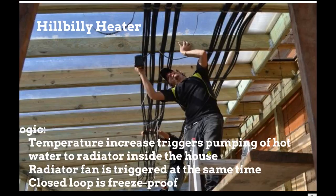So let's talk next about the heating system. The Hillbilly heater is just a passive solar thermal heater, a closed loop system that we're running into the house with a fan radiator. And the logic there is, once it's daytime, it's hot, this is winter, let's say, and a certain temperature is reached, you start pumping the fluid into the heat exchanger inside the house, and you turn on the fan to spread the heat in the house. So you're transferring heat from the greenhouse into the house, which is a simple thermostat controller that works with a radiator that does forced air as well as pumping of the fluid inside this Hillbilly heater.